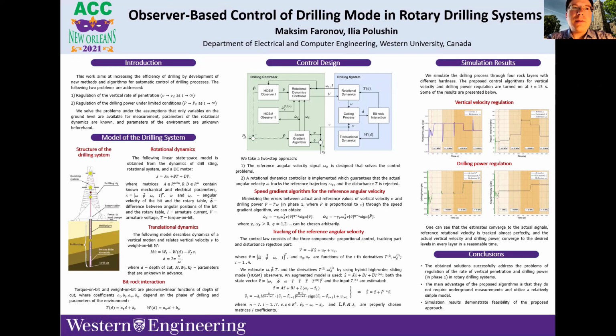We use a rather simple finite dimensional model of the drilling system, where rotational dynamics are represented by a system of linear differential equations with the motor voltage as a control signal and reaction torque, or torque on bit, as a disturbance. It is interconnected with the translational dynamics and the bit torque interaction through a nonlinear component, which is called depth of cut.